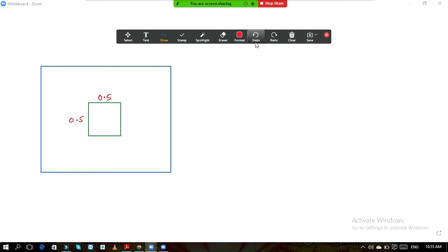Now you know that the critical section is at a distance of D. So I will draw the critical section. In the case of one-way shear, we will take the critical section at a distance D, but we will take it once along X direction and once along Y direction. In punching shear, we take the critical section at a distance of D by 2 from all four sides.